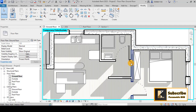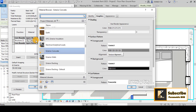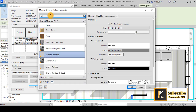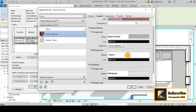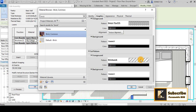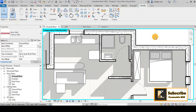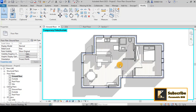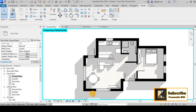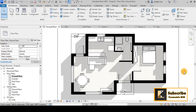Maybe the interior walls also need to have some materials, so I will go to the materials here. Maybe I can find something like brick. Yes, I have this brick. Maybe for the cut pattern it is good, or you can change it as you want and change the scale as I showed you. So I will go OK, and you will have this representation for the interior walls. And also if I turn back to the course, you will have this color that we assigned to it. I think this is enough for this tutorial.